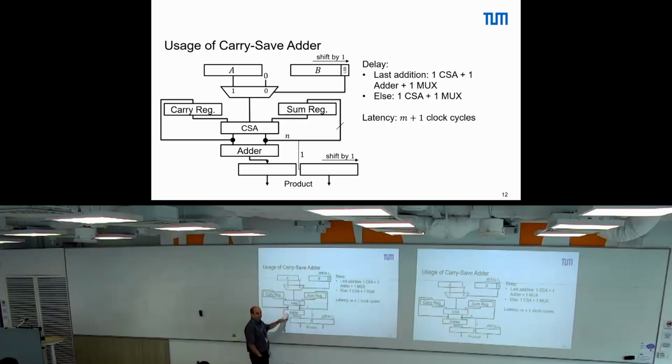Now, what can you do? You can run with the speed of that one, and then implement some wait cycles to ensure that this adder has sufficient time to compute the final result. One option. Another option is you just remove this and continue running the CSA. So if you continue running the CSA, then what happens is that for a while you have here zeros implemented, right? So virtually that means you sum up always then the carry and sum bits. So you implement actually a serial adder then for all the different positions, and you sum up until the result is settled. Then you can further run with the speed of the carry save adder. Make sense? Or was it maybe a little bit too confusing?